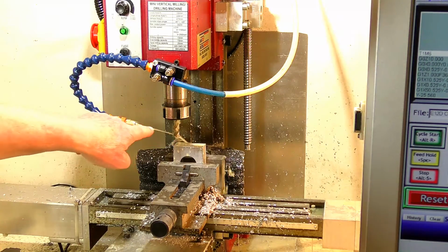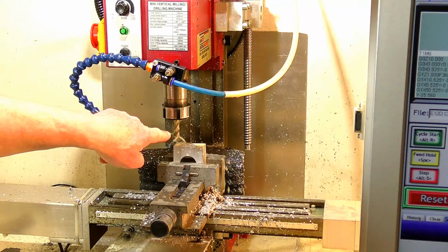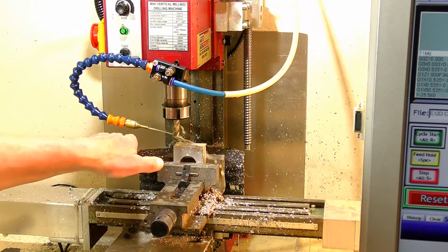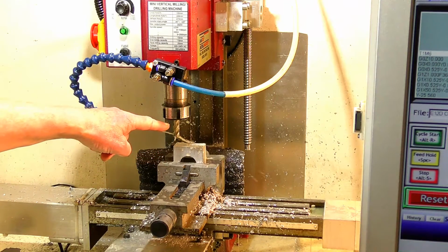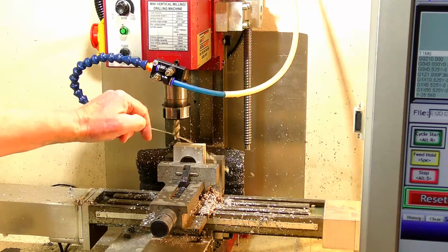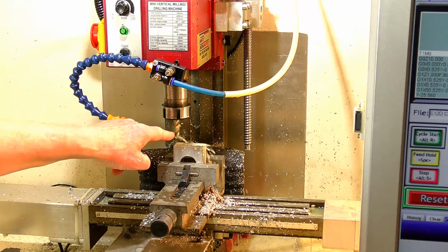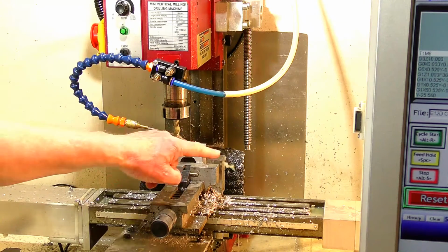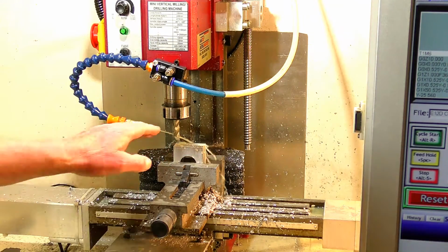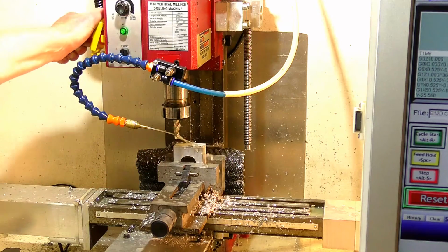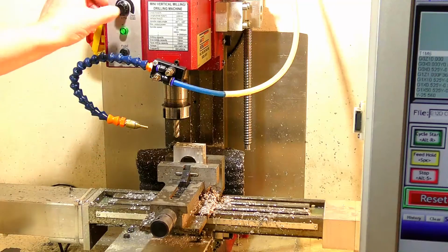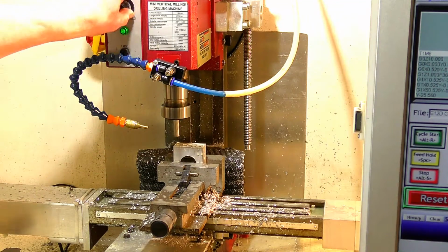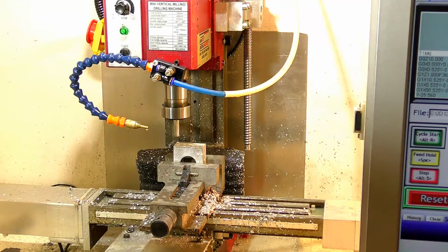So what we need to do is just run the coolants on the tip, because we're cutting. We're not going down into a pocket where I have to run the coolant all the way up here and let the tool carry it in. We need to flush the material off the end of the cutter, keep it nice and cool. Let's turn it off a minute, otherwise I'm going to get splashed. So, here we go.